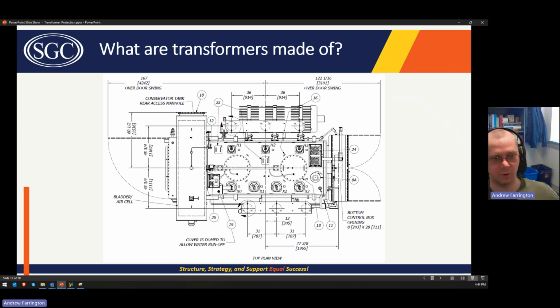If you mirror it, now it's like you've flipped the transformer upside down. There's no orientation on this transformer where you could ever have the bushings H3, H2, H1 if the high voltage winding is towards the top of the page, right? The only way you could do that is if you actually took it and flipped it over, right?